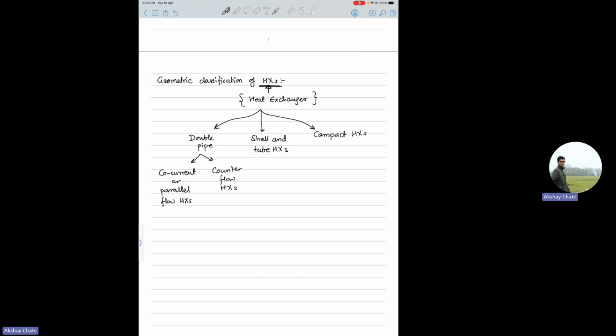So these are plate fin type heat exchangers, typically used for gases because otherwise the pressure drop for liquids is high when the dimensions of the channel are small. So this is the overall set of practical geometries of heat exchangers. We'll take some problems amongst these, but in our problems it may not depend on geometry that much. But in practical applications, if you are doing higher studies and want to design an experimental setup, then you have to look at the geometric classification also, so you should have some idea.